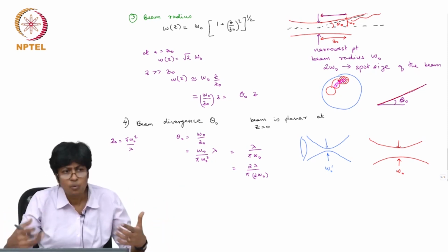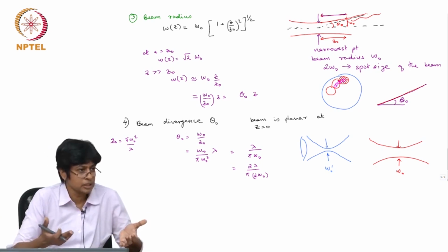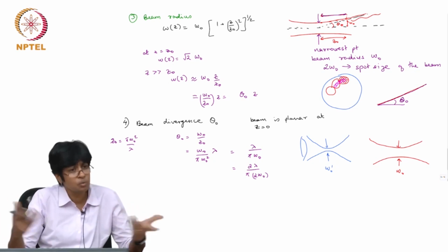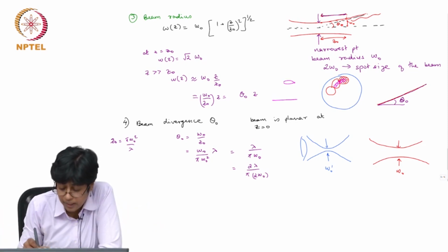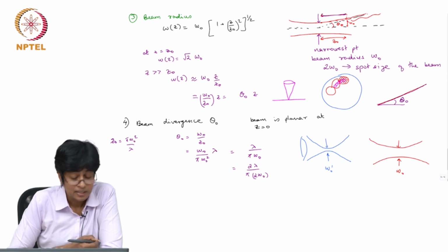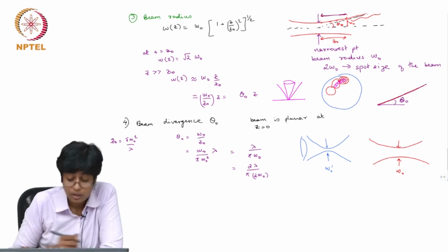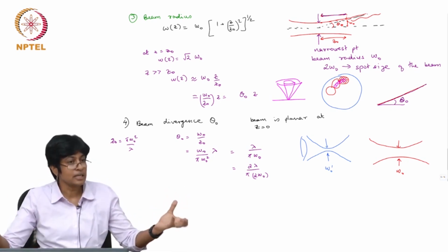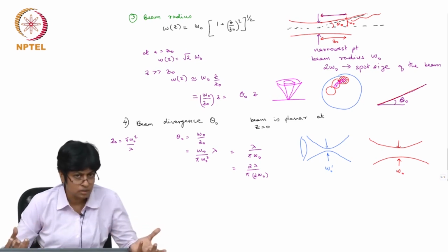Now you might ask, so what? I want to capture or store a lot of information or read out a lot of information, and I can do that if the beam size is very small. Who cares about the divergence? But remember, in the CD pickup, you had a lens, you had the disc, and you were focusing onto this. Now, the finer you're focusing, it means the larger the beam has to be, which means your optics has to be larger. So then you're making your system larger in order to achieve smaller focus. In some systems that might be fine, in others not so.